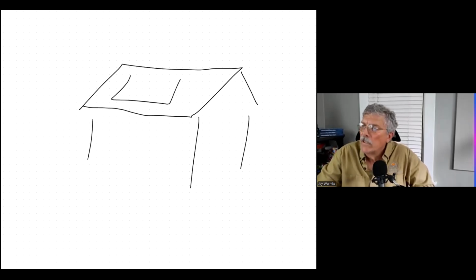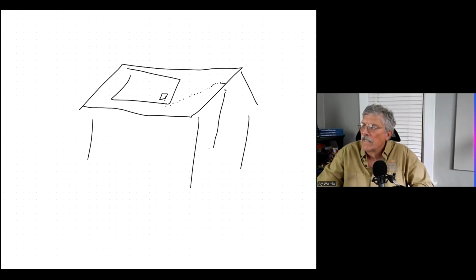And the way we used to design these systems is you'd probably put your combiner box or your junction box underneath the array, and then you drill a hole into the attic, and maybe you put the wire on the underside of the rafters or whatever, possibly pop out of the building over here, come down to a DC disconnect.